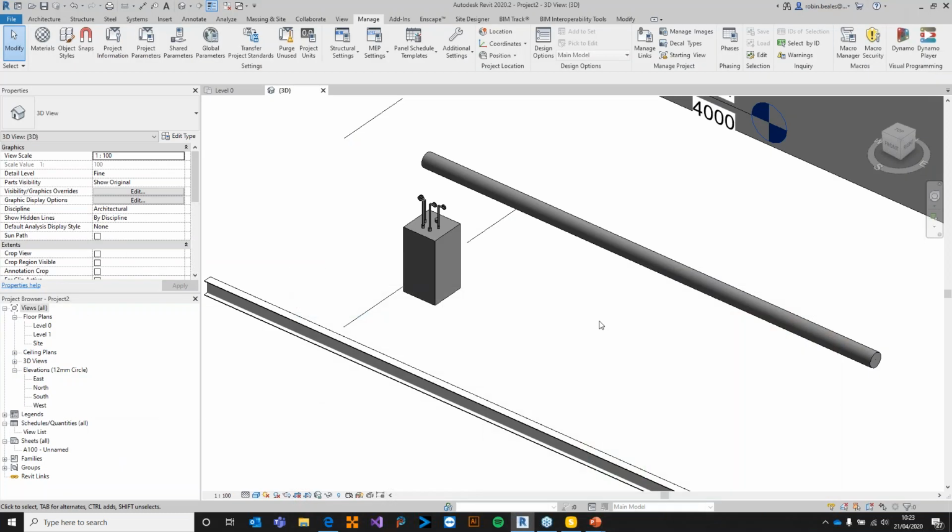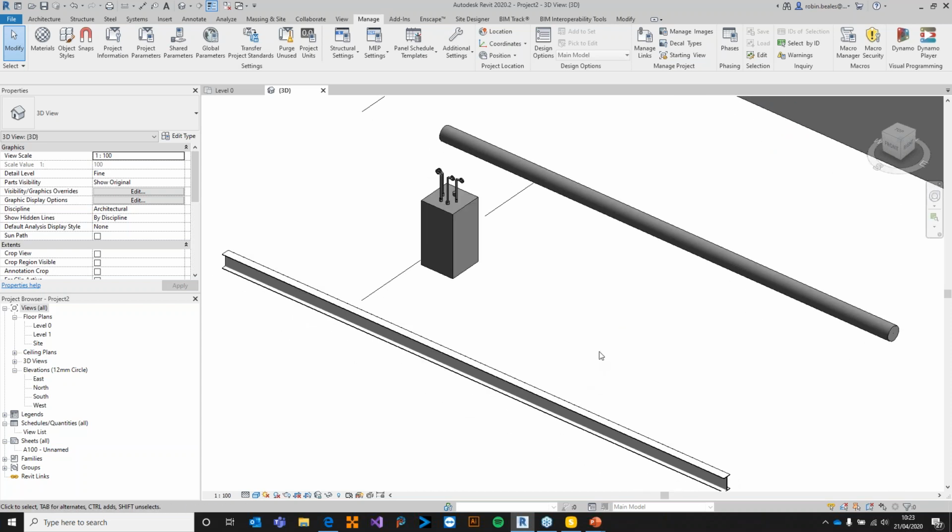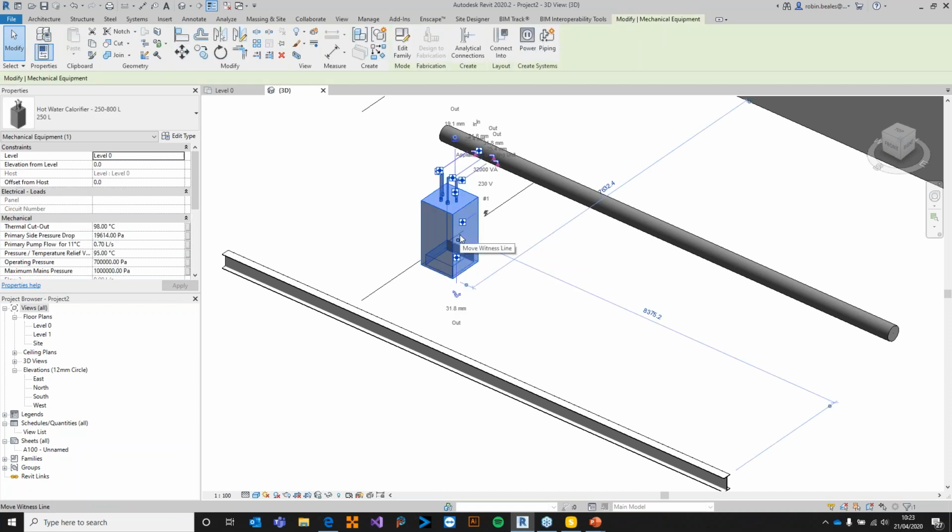So that's kind of the biggest thing that people need to be cautious and careful of in an IFC, is that those objects are not subcategorized correctly. It's quite a big job, if I'm honest. It's a very big job to go through and make sure that those generic export settings are correct, and you also have the per object correct. Per object will override the generic, okay? So just be wary. You also need to be careful because those per object ones can do complete overrides.